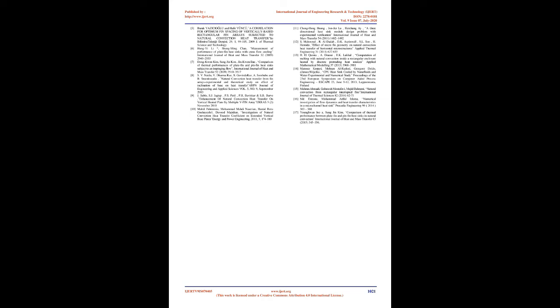When the base surface of the fin increases, the air present near the surface of the fin moves vertically upwards with high velocity. In the case of high thermal conductivity materials like copper, the thermal boundary layer is found to be wider, resulting in a higher heat transfer rate. In the case of aluminum and steel, the non-uniformity in temperature and heat flux distribution results in a reduction in the thermal boundary layer. Based on Nusselt number, with an increase in fin spacing, the heat transfer rate also increases. Copper is often used for high thermal performance in heat transfer applications; aluminum is found to be more appropriate where the mass of the microfin is significant.